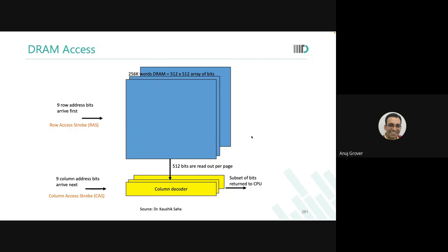Look at it like this. If we go back to the SRAMs, the column address is used to decode bit lines to be connected to the sense amplifier. Now in DRAMs, we saw last time that as you read, you have to write back on every bit line that is selected.